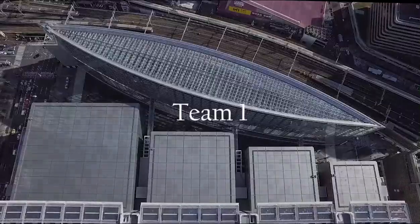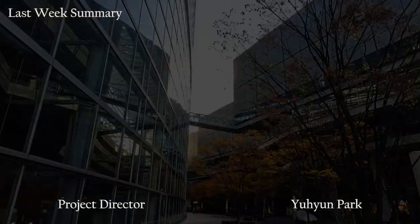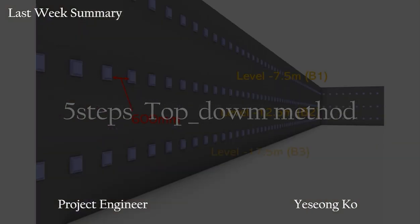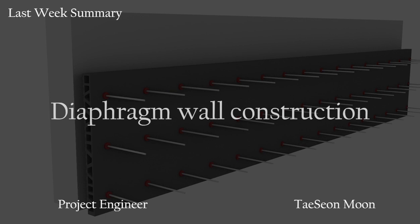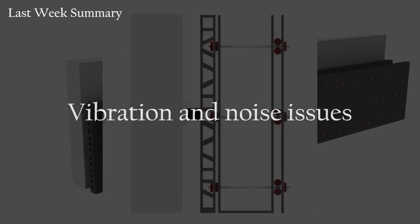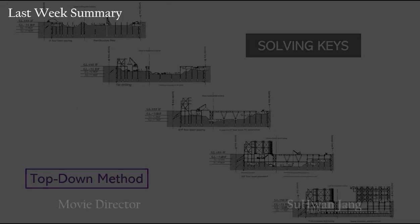Over the course of our discussions, we have covered several crucial techniques and challenges involved in the construction of Tokyo International Forum. We focused on 5 steps of the top-down method. Additionally, we explored the diaphragm wall construction method, which is crucial for ensuring the structural integrity of the underground levels. We also addressed the issues of vibration and noise caused by 4 subway lines running near the construction site.